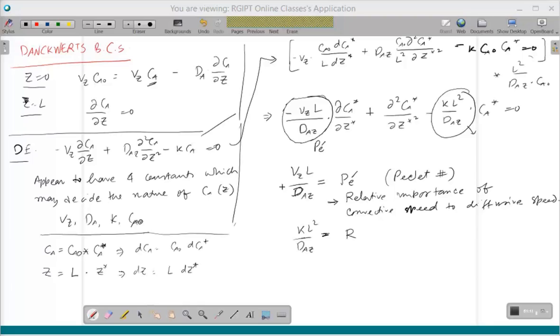Suppose there was no reaction, and there was a flow, and you entered a speck of dot or probably an ink somewhere over here. As this reaches the other end, this does not spread much. The ink spot quickly moves from this end to that end without spreading much. That would be basically high Peclet number.